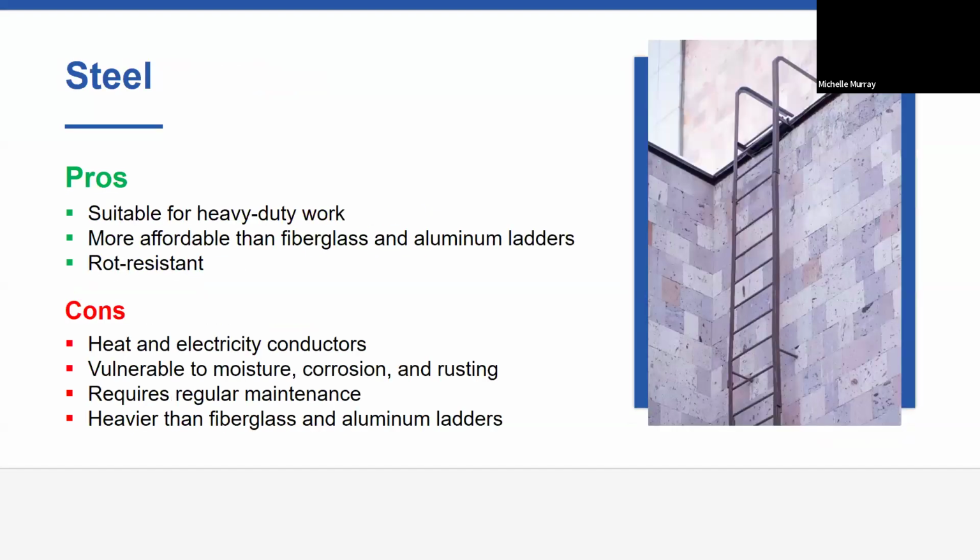Steel ladders are good to use in rough environments, such as a warehouse or industrial facility. However, it's important to note that steel ladders are not corrosion resistant. If you plan to install it outdoors, you'll need to have it galvanized, painted, or made with stainless steel to meet ladder regulations. This can add to the ladder's expense.